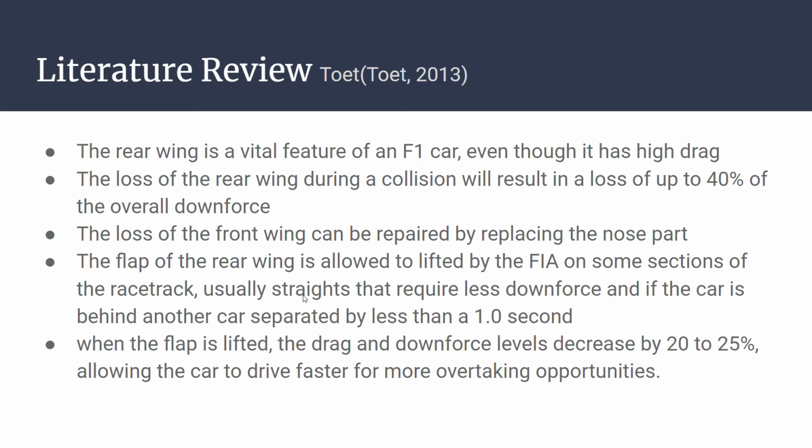This is only permitted to operate on some sections of the racetrack, usually straights, that require less downforce, and if the car is behind another car separated by less than a second. Towett also stated that when the flap is lifted, the drag and downforce levels decrease by 20 to 25%, allowing the car to drive faster for more overtaking opportunities. That's all from me.